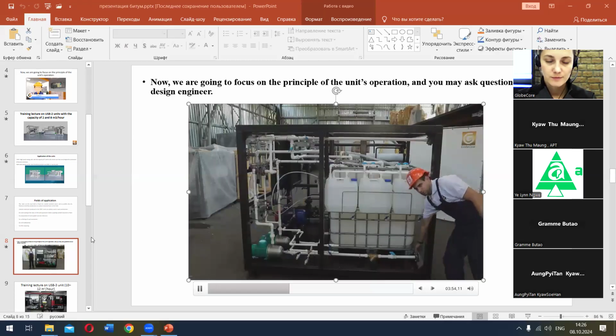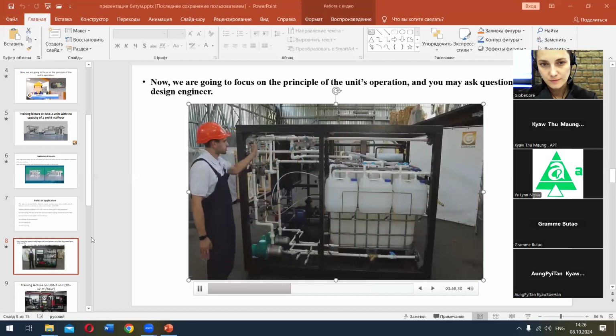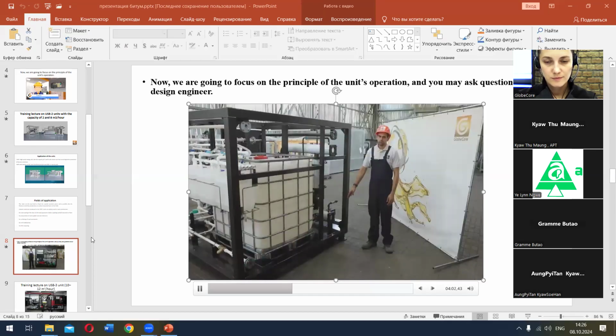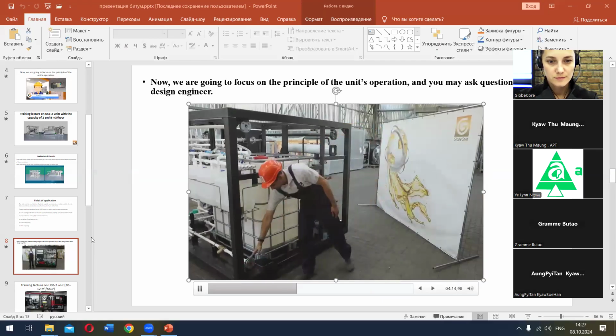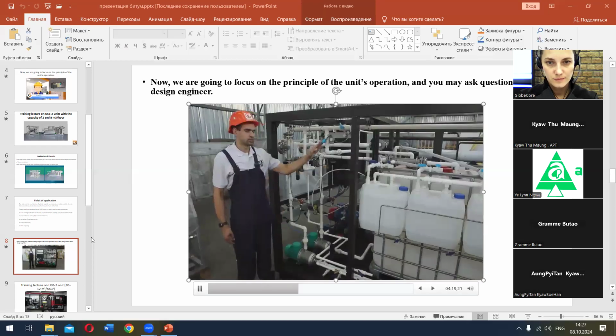Next, the previously heated water is supplied to the water input pump and circulated to ensure temperature normalization. The heated water is supplied to the inlet pipeline, enters the pump, and flows through the return pipeline back into the heating tank. Hot bitumen is connected to the unit through the inlet pipeline, the return pipeline, and the emulsion pipeline, which means the finished product pipeline.